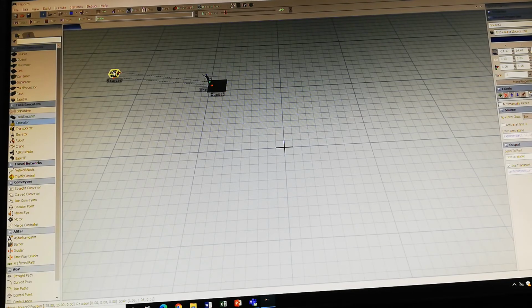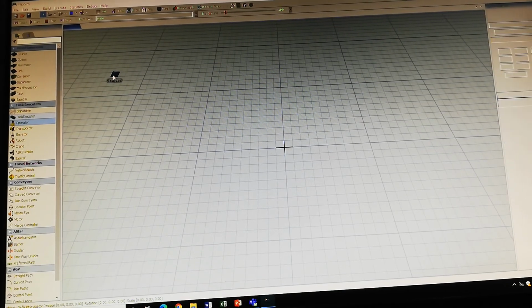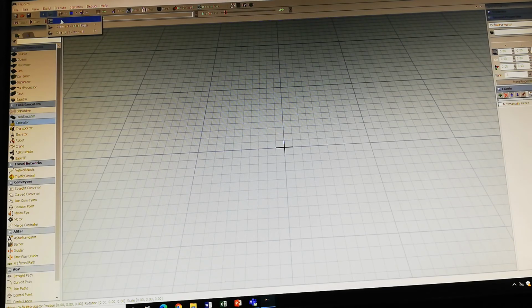This is not difficult, but it is important to consider something. I am going to eliminate everything. It is important to consider that when you have in this menu the options connect center port and connect objects, when you have a mistake or a problem, you can remove it by selecting the next option. The next option says disconnect objects and disconnect center ports. You only indicate what is the movement to remove, and it will be eliminated.